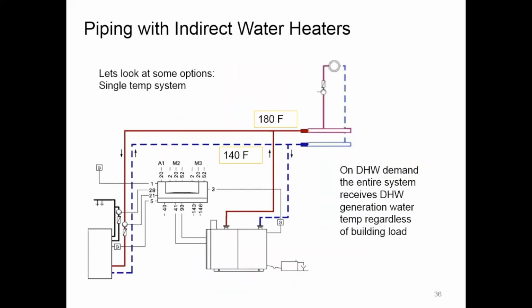Other things we take a look at is the use of mixing valves in applications, particularly applications where I may have long periods of time where the boiler has to come to an elevated temperature for a specific load. This happens to show water heating. It could be domestic hot water. It could be a pool or a spa. It could be snow melting. It could be reheat for air conditioning with another load on top of it, underneath it.